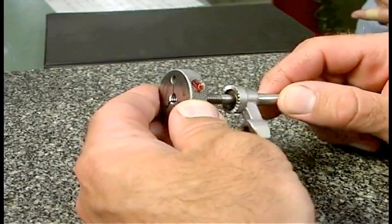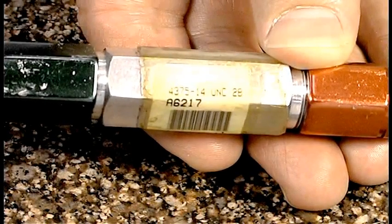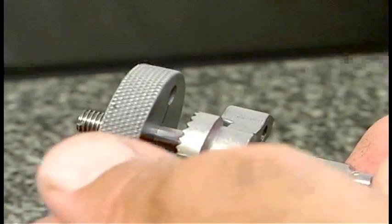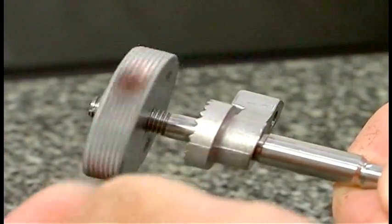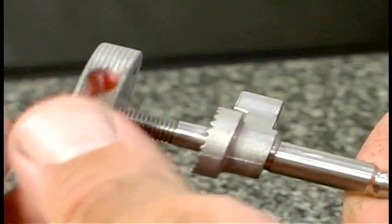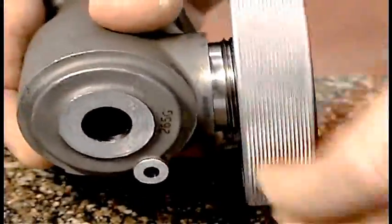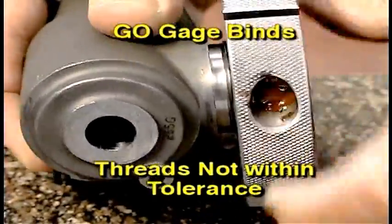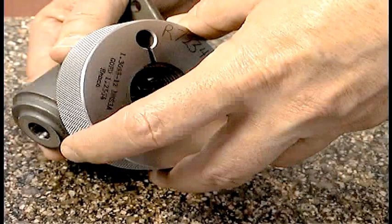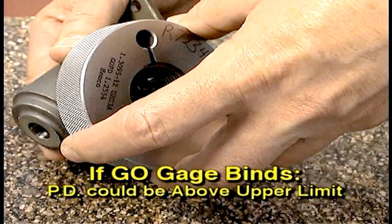Go, no-go ring gauges may be used on OD threads. Each gauge is marked with its specific thread size. These gauges simultaneously check many attributes of the thread form, such as angle, taper, roundness, and lead. Thread the gauge over the entire length of the thread. This gauge begins to bind as the gauge moves toward the shoulder, indicating this thread does not meet tolerances. When the go gauge binds on the threads, the pitch diameter could be above the upper limit.